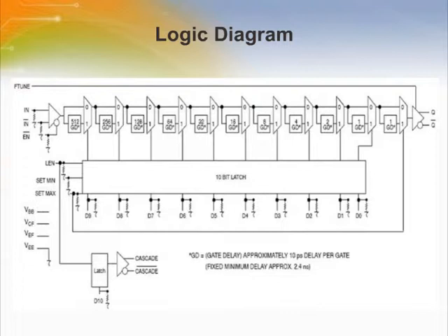by the LEN pin. A low level on the LEN pin allows a transparent load mode of real-time delay values by D9 through D0. A low to high transition on LEN will lock and hold current values present against any subsequent changes in D9 through D0. The approximate delay values for varying tap numbers correlate to D0 through D9.